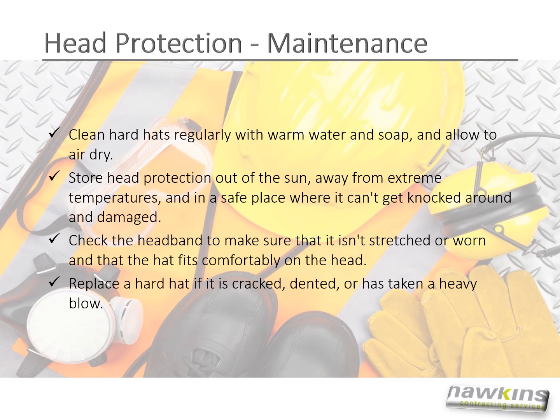Do not neglect maintaining your hard hat. Clean hard hats regularly with warm water and soap and allow to air dry. Store head protection out of the sun, away from extreme temperatures, in a safe place where it can't get knocked around and damaged. Check the headband to make sure that it isn't stretched or worn and that the hat fits comfortably on the head. And replace a hard hat if it is cracked, dented, or has taken a heavy blow.